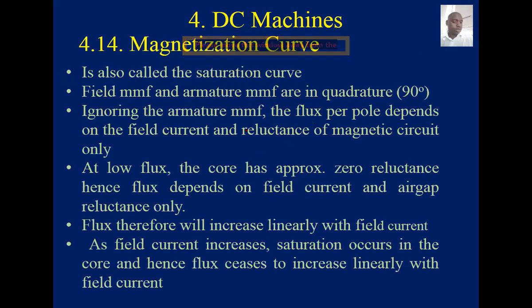So that's basically how you make calculations using those parameters of the machine. Now, we have made some assumptions about a machine so that we can simply go and make those calculations. But you realize that the conditions tend to change. So you realize that we've put a linear relationship between flux and the speed and generated EMF and developed torque and so on. But the reality is there is a point when those relationships cease to be linear.